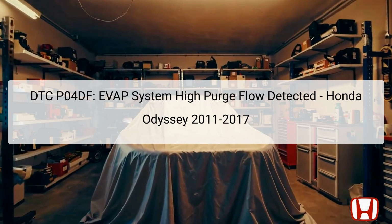the atmosphere. Key components involved in this system include the evaporative fuel tank pressure sensor, FTP, the EVAP canister purge valve, and the EVAP canister vent shut valve. These components work in conjunction to regulate the pressures within the fuel system and facilitate the purging of fuel vapors into the engine for combustion.